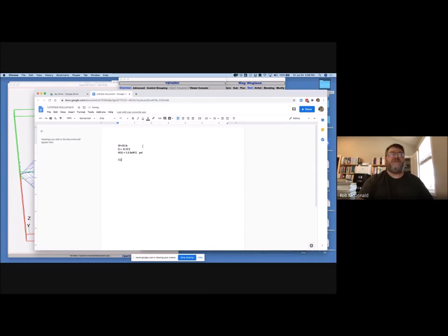Your lift coefficient equation, CL, is equal to W over Q times S, where Q is your dynamic pressure, 1/2 rho times V squared. So you'll notice CL, this W over QS, well, W over S is your wing loading over Q. And here in Q, rho is your density, which really means your altitude. Are you looking for things in the Himalayas or at sea level? That's going to determine your density. And your V squared is obviously your speed.